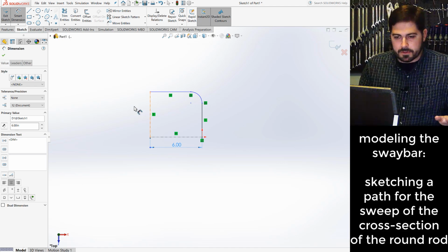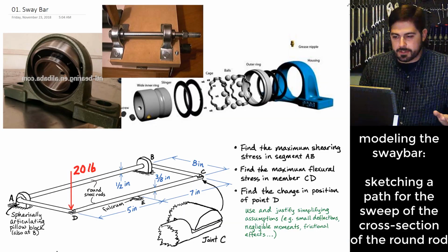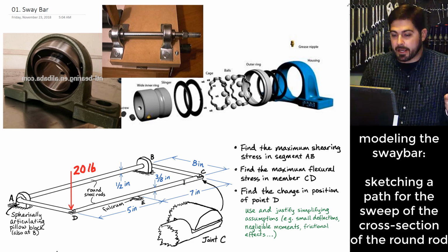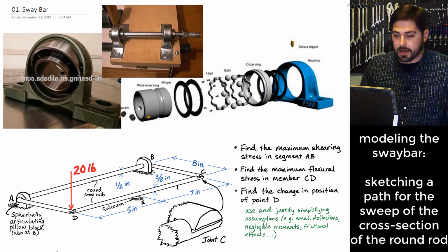The other one's a little bit more tricky, because if you look at this, it is 8 inches from point B to point C, but in reality, we need that member BC to be just a little bit longer so that it overlaps enough with my other piece. So I'm going to have it be long enough to cover not only the theoretical point C, but also overlap by 1 radius of rod CED.